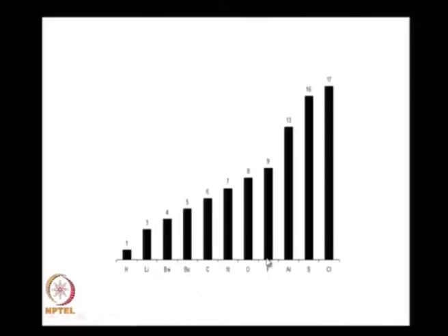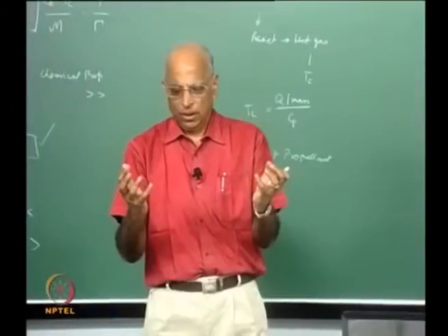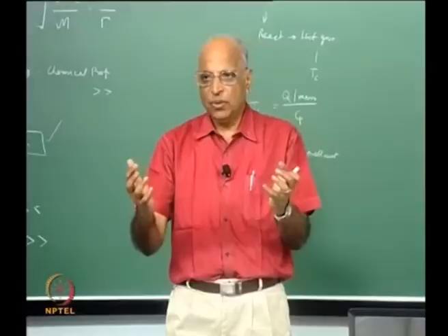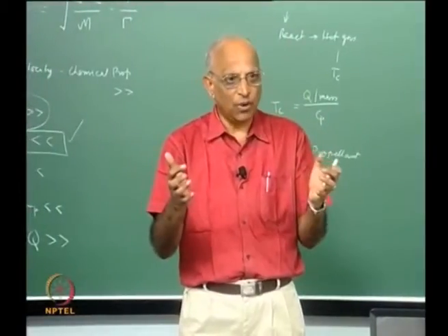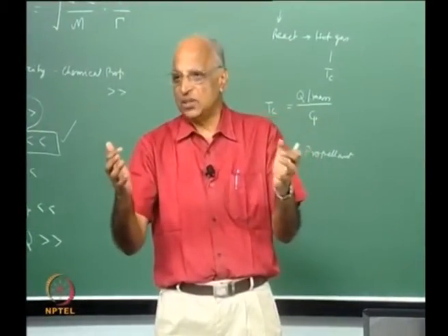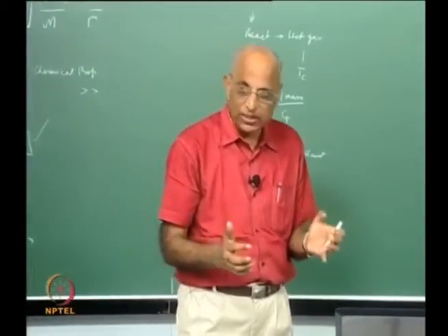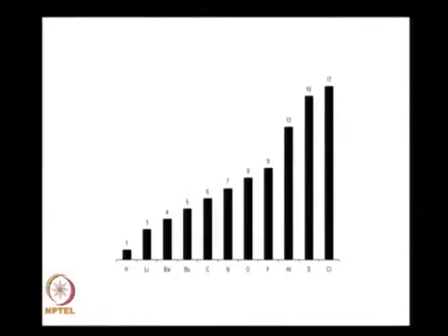Well, fluorine is very reactive, it is more reactive than oxygen, and in fact they did try to use liquid fluorine for rockets. It just used to corrode the tanks itself, and therefore it was used in one of the Delta missions, but subsequently I do not find it being used. But anyway, we will keep it here, we will see under what conditions fluorine can be used. Well, oxygen, fluorine, chlorine are oxidizers, maybe hydrogen is a fuel, lithium, beryllium, boron, carbon and aluminum are fuels. Aluminum is a metal which can burn.